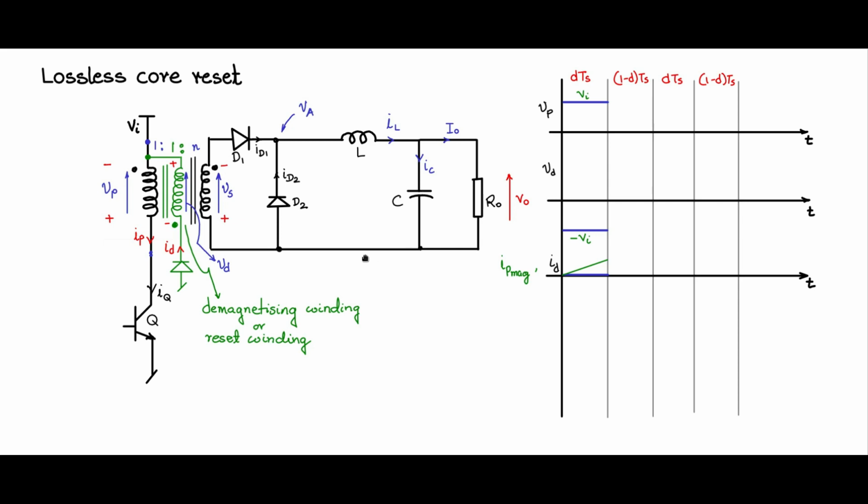On this secondary side, the inductor is freewheeling. This is plus and minus in this fashion. This diode is reverse biased, so the entire secondary is like open circuited. We will not talk about that. We will talk only about these two. Now here, the non-dot end is positive, and this will become as positive as it can to pump against this Vi and make this diode forward biased, so that the diode is conducting for freewheeling action.